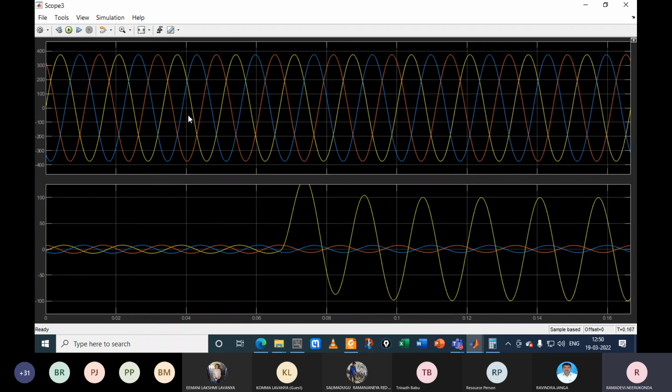So these are our voltages and currents. So 54 turns are short circuited in one coil. So one entire coil is short circuited. Because of that, we get a huge current change in the corresponding phase. Okay. So this is the phase corresponding to the R phase. But here the color indications are different. But we created the fault in the R phase.